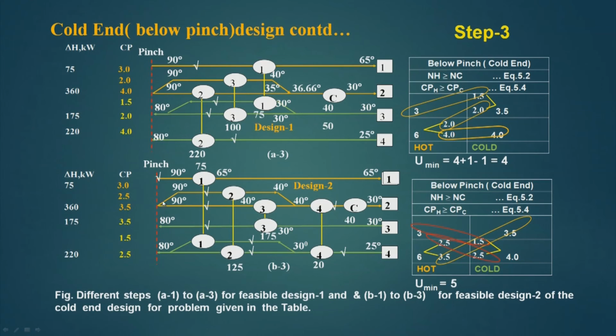Now, this part now contains 90 minus 40 into 2.5, 90 minus 40 into 2.5 comes out to 125 kilowatt. Now, this stream has now 125 kilowatt. So, using heat exchanger 2 I am transferring the total heat to this as 125 heat.